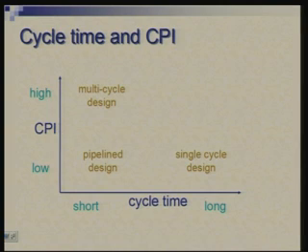Now, one thing we must notice is that if you focus your attention on a particular instruction, the instruction is still taking multiple cycles. Instruction has to go through several stages, and it completes its action only after multiple cycles, but the rate at which instructions are initiated, the throughput, is higher. So, ultimately when you are executing a large number of instructions, it is the throughput which will matter. For a large program, we are not worried about how long one instruction took individually. We are worried about the rate at which instructions get executed, because that will ultimately determine the time.